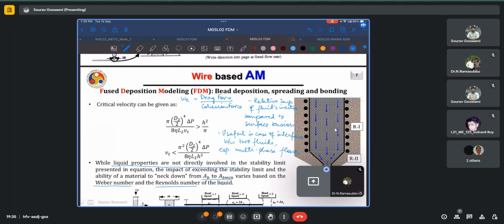The Reynolds number is well known. Still, just for the sake of completion, I'll also write its physical significance. So it is simply the ratio of the inertial forces to the viscous forces. And quantitatively, we can say that for a laminar flow, the viscous forces dominate. So if the value of the viscous forces is high, the Reynolds number would be low.